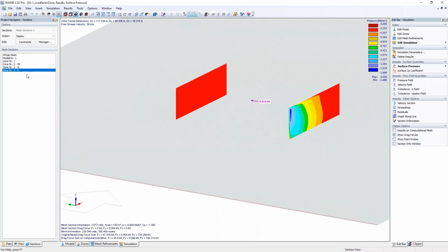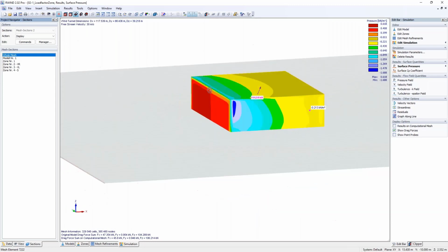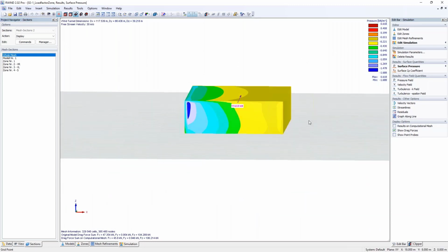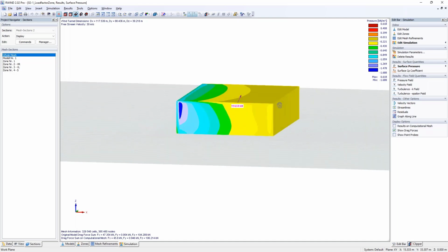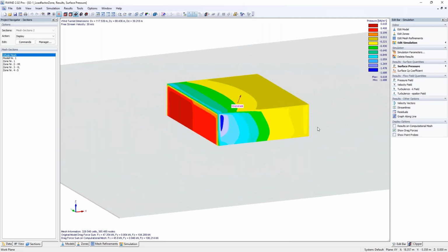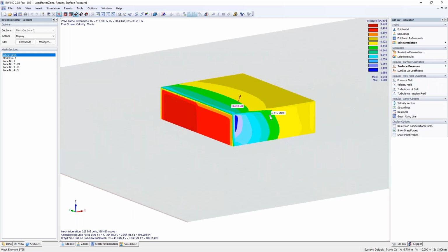And the main focus for this is, imagine that maybe the wind analysis has some weaknesses, because the steady or stationary calculation can maybe not really capture the suction at the backside of a building. You could just define a zone there and increase the value. Or if you think that you will have to add some special safety factor, you can as well increase it. Or if you think it's way over the top, you might decrease it. And then if you hand it over to RFEM 6, the loads will also come with the factor. So you do not have to rearrange or multiply them later on in RFEM 6.